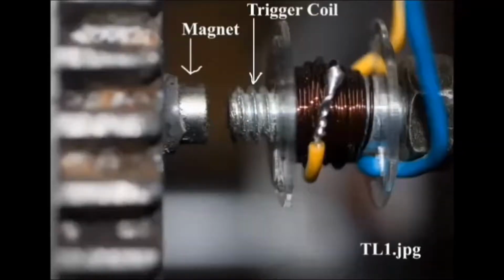And if we put the oscilloscope and all that stuff aside and take a look at the actual spark location with a timing light, what I found on the setup on the simulator was that the spark was occurring as the magnet was at the trigger coil. It's very close to being centered up here. This is different than I have found in the past, and fortuitous, and it makes it pretty simple in our planning for the timing for the spark.